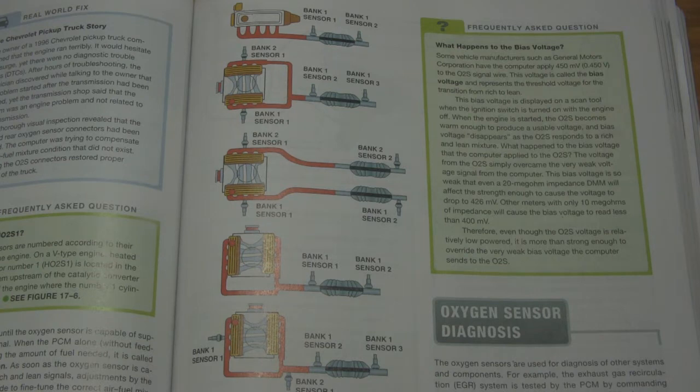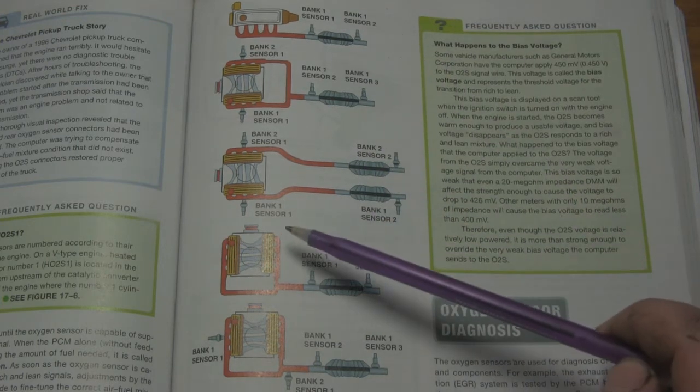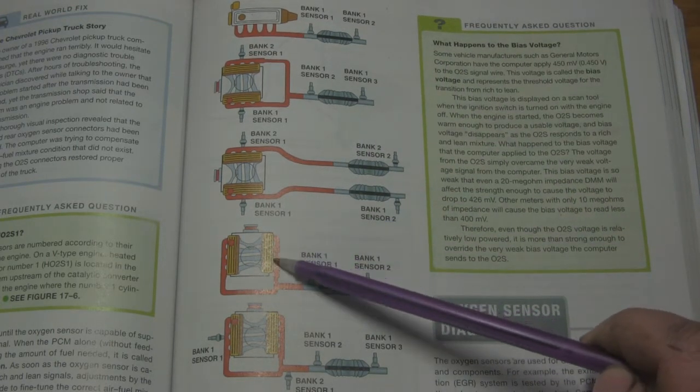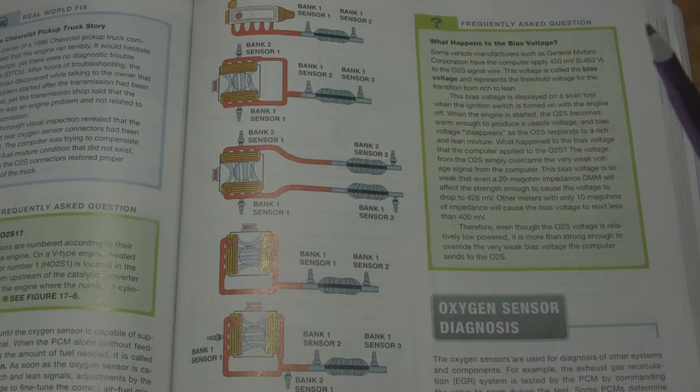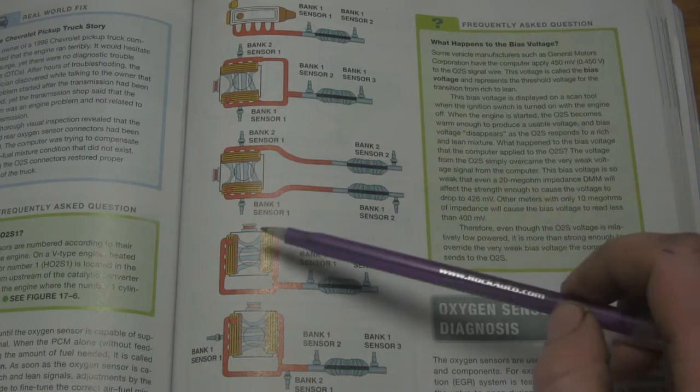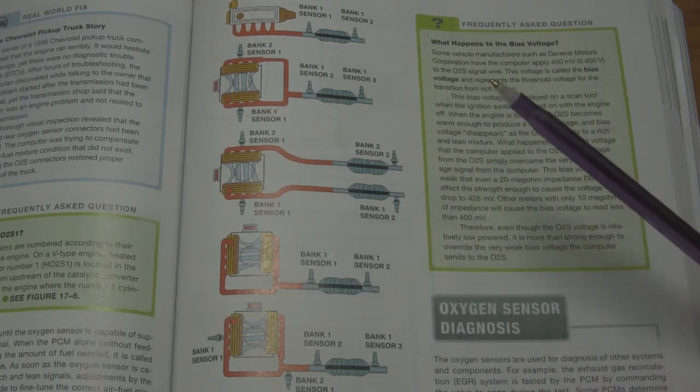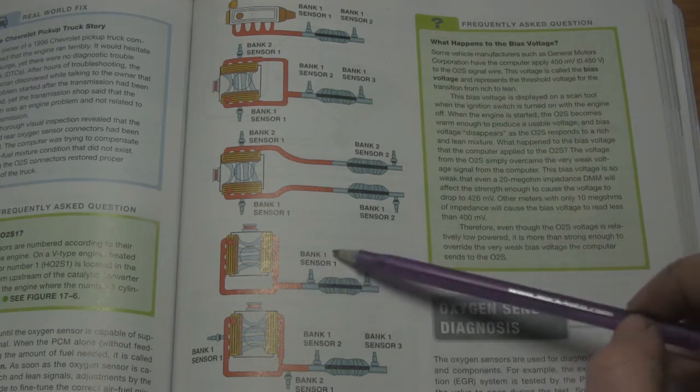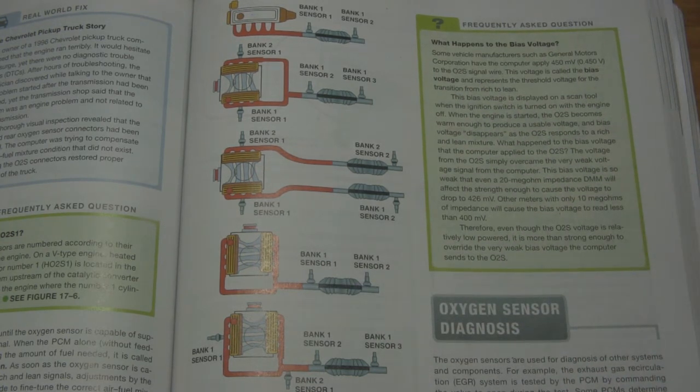And what you're actually seeing is manufacturers are moving closer and closer towards going to the individual cylinder bank. And so there are some prototypes out there, and there are some test engines that I've personally seen where each cylinder is its own bank. And if you think about it, that allows for even finer tunability in the event of a cylinder misfire, or overall emissions might be elevated on that one bank due to that misfire and the consequence of the oxygen sensor seeing a whole bunch of extra oxygen. We can now trim out just the one cylinder that's causing the issue and not affect all the cylinders.